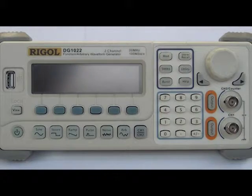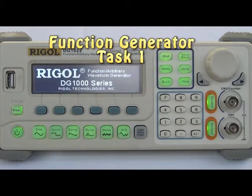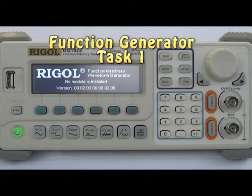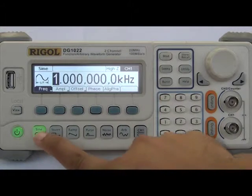First, switch on the function generator. This task is to set up the function generator to generate the sine wave as shown in figure 4.1. At the start, press the sine button.